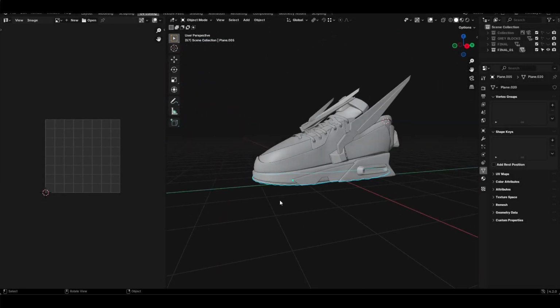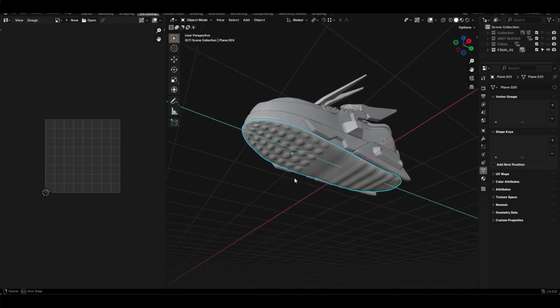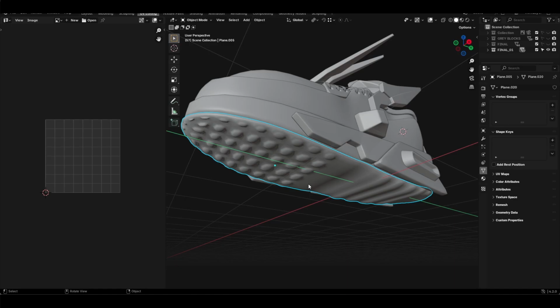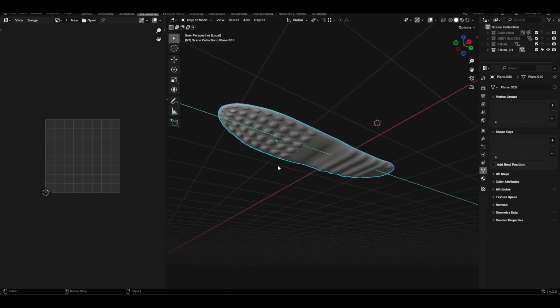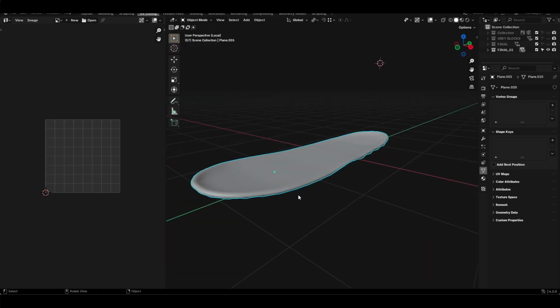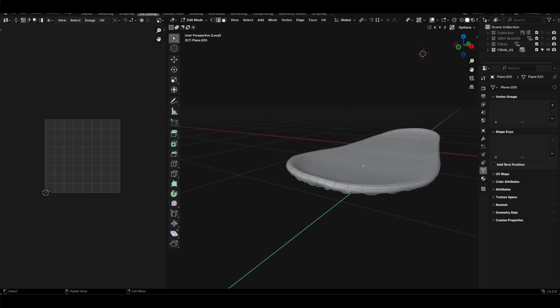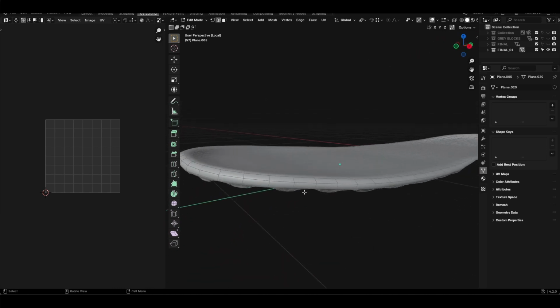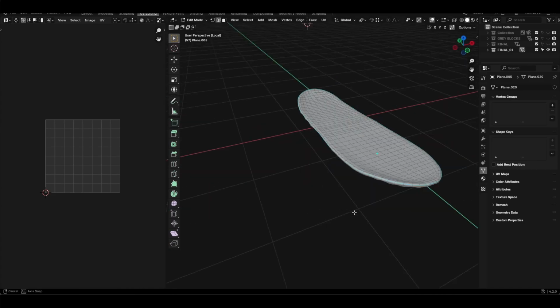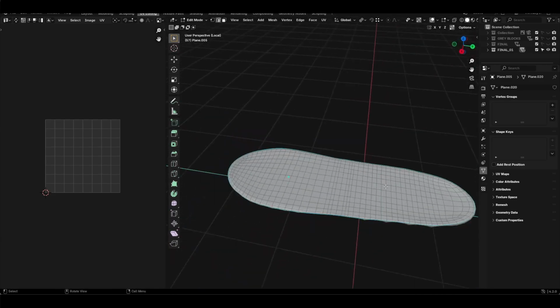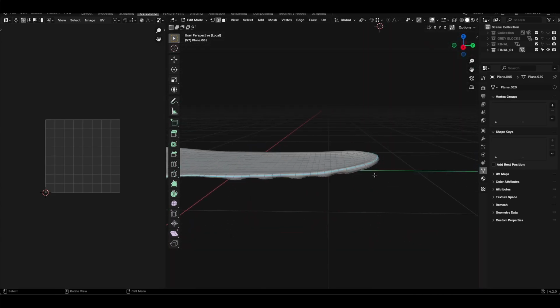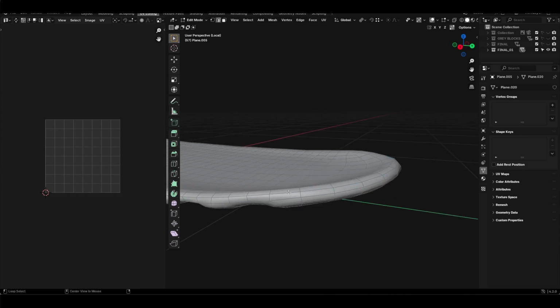Okay, so let's say I'm gonna UV this one first, the bottom. So let's say I'm gonna toggle local view, then go to edit mode and press 2 on your keyboard to activate edge mode, so that you could select edges here. Then I want you to hold Alt and click this so that it will automatically select around the mesh. So all the edge flow will select everything like that.